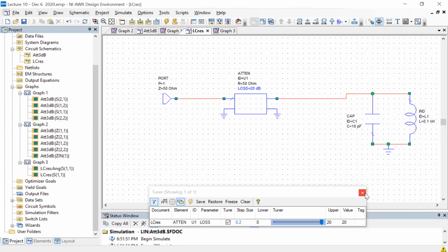So a filter is a two-port network, so it will have S21 and S11, and it's symmetric, so the other two parameters are the same. So if you're only interested in S21, which is true for most filter characterizations, then this is a reasonable thing to do.